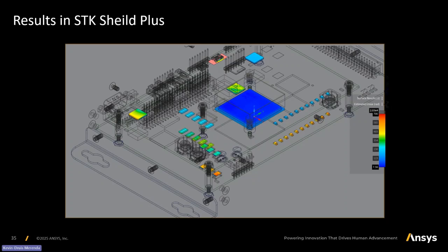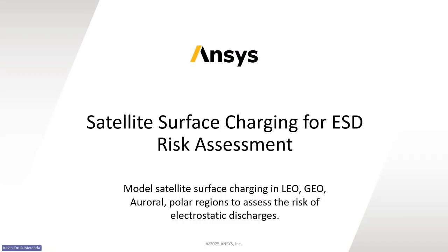And so here we're able to see that some of the components that are close to a surface near a connector on the top here, where there's a lot of gaps, have a very high level of radiation compared to some of the components on the inside, for the dose depth curve that was chosen and generated in this setup. So this is very powerful to be able to do these analyses and make sure that you stay below a certain threshold for a change in environment.